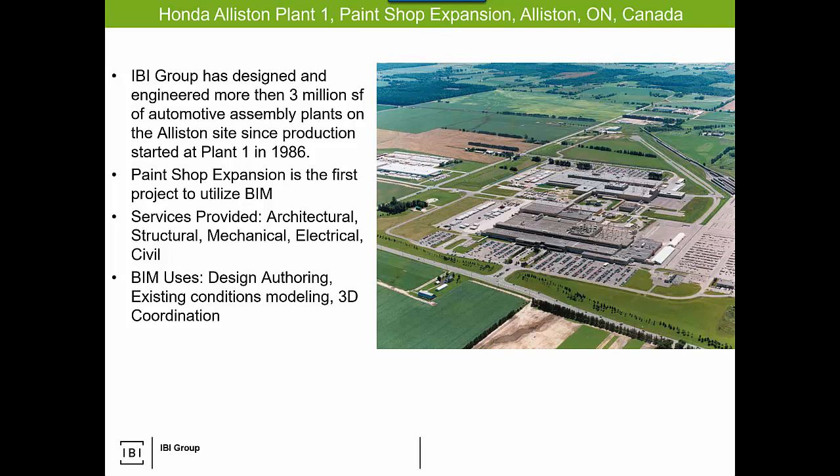Do you BIM the connecting points? When I worked on some industrial projects in the past, we would BIM the points of interface. So maybe 5 meters into the existing building, only at the interface points, so that you can ensure coordination. But think about electrical and mechanical specifically. They're interacting. So how much do you BIM? Are you expanding the mechanical system into the expansion, or are you setting up a new one? And if you're expanding and they want to maintain airflow calculation and full intelligence relative to the mechanical system, they probably need to model the whole thing. But then to what extent?